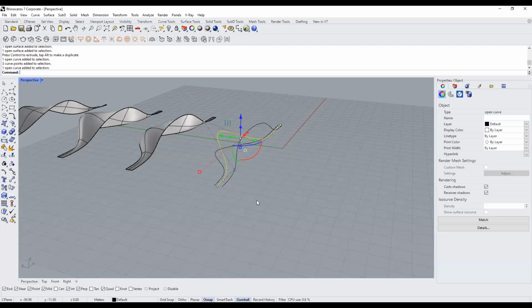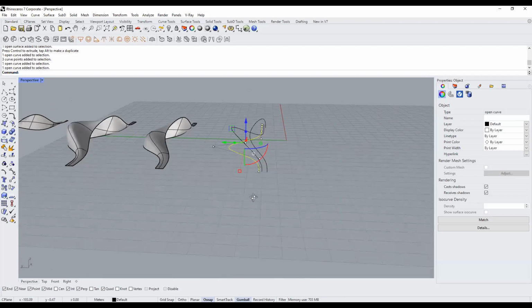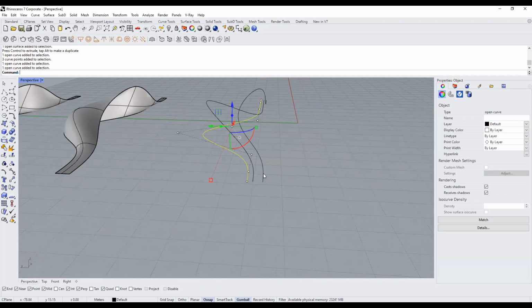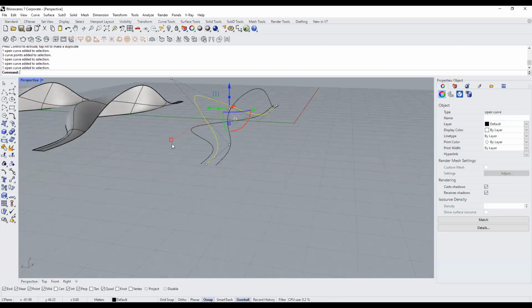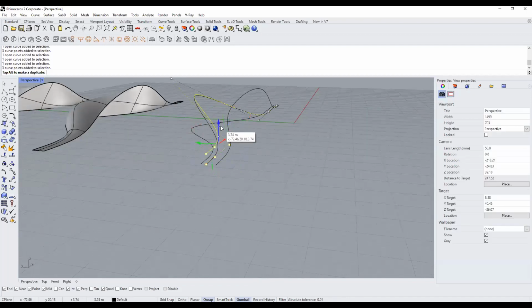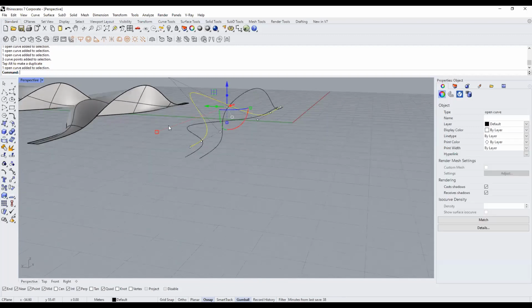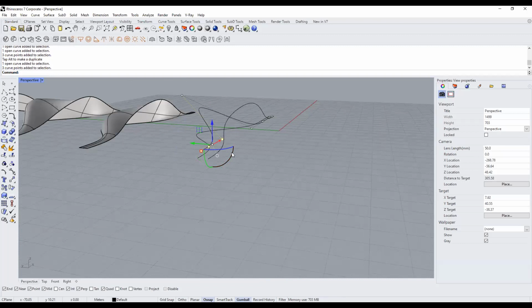Like your last curve, which you copied, all of those are on the x-axis, right? Like that, if I just want to bring one point to the x-axis from another curve. You can do that too, yes. So let us say only these 3 points are moved above. And I do not want that. I just want these 3 points to come down to the flat Z axis. The rest of the points have to retain their curvature.